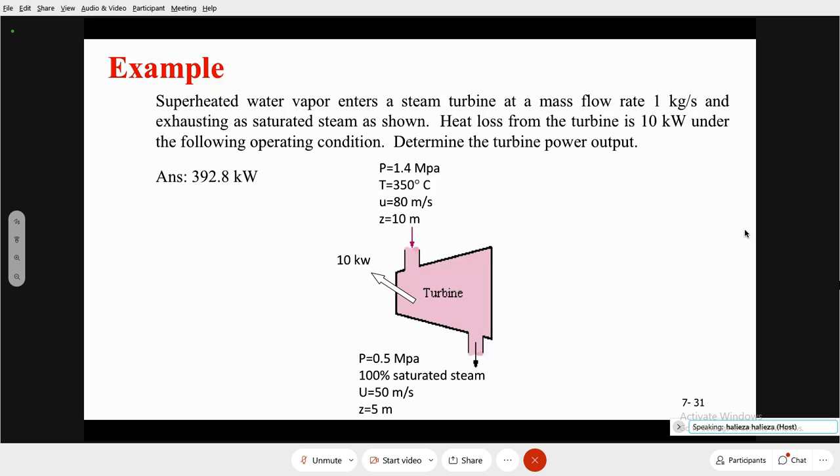The convention of sign. Okay. Should it be negative, guys? It depends on how you say it. Yeah, but common sense. Now that we are using the negative to be the outlet, that means the power should be out. Remember, look at the question itself. Determine the turbine power output. Yes, output is supposed to be negative. So we should be getting negative.